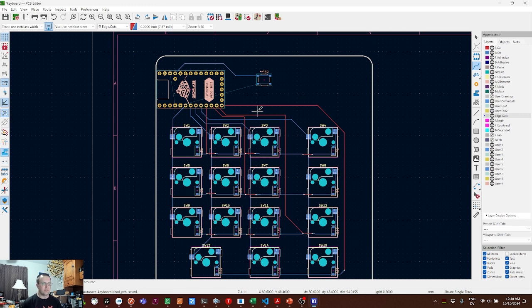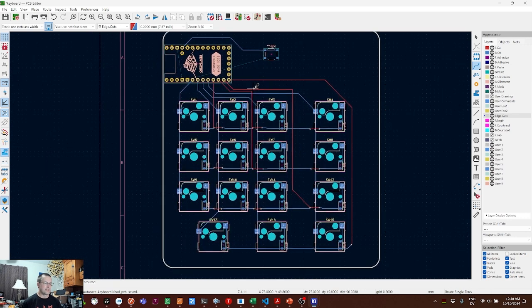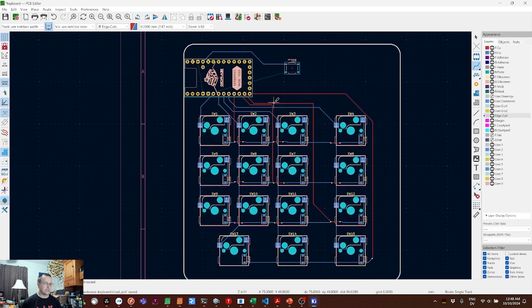That gets really important when you're dealing with high bandwidth signals, high megahertz clock signals, all kinds of stuff like that, USB data lines. We're not dealing with any of that. This board is about as simple as it gets. Nothing's moving at a high data rate. I don't think a ground plane is going to make a difference, but it's good practice. It's how you deal with electromagnetic interference, basically.